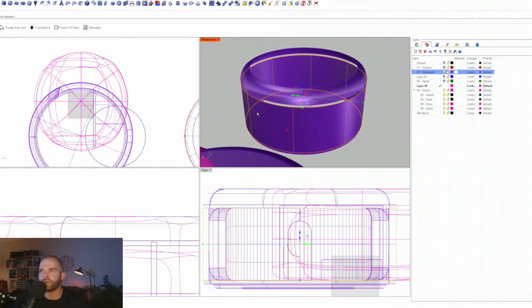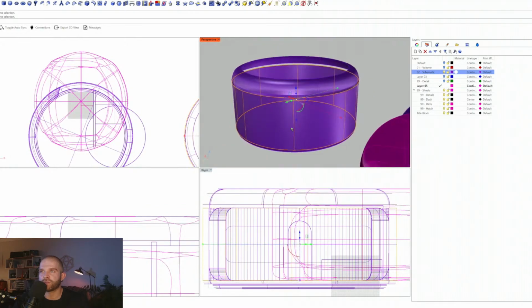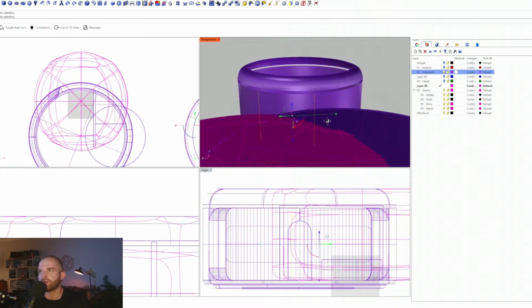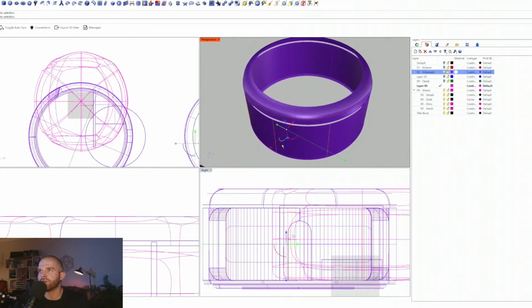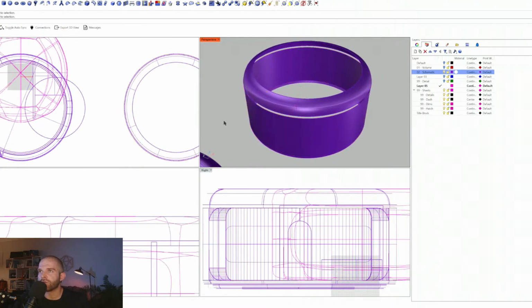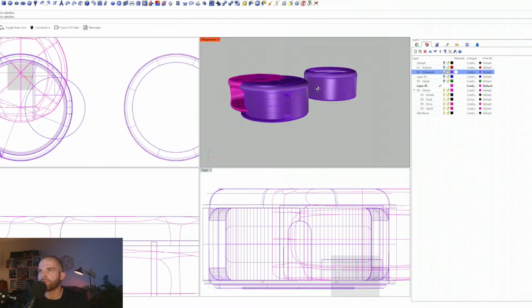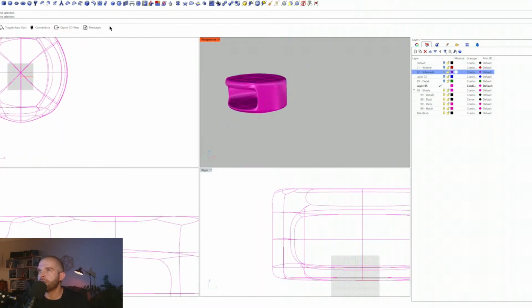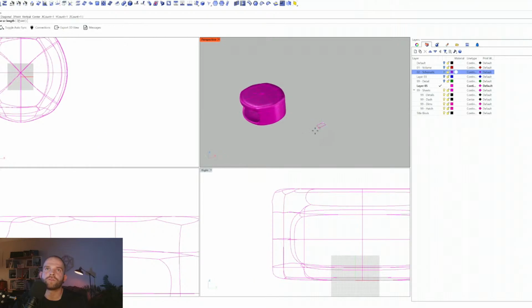Cool. So we see now this is a SubD. It's a perfect cylinder. We could start building out from here as well, now that we have this. So if I were to just scale this flat, sort of, I could have done that more gracefully with Scale1D. But yeah, we can take that route. We can also do that from a mesh. So if we have a mesh, let's see, mesh tools, we do a mesh box, or let's do a mesh cylinder, keep it consistent.